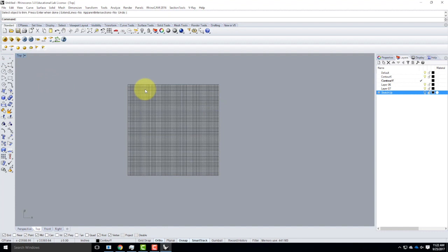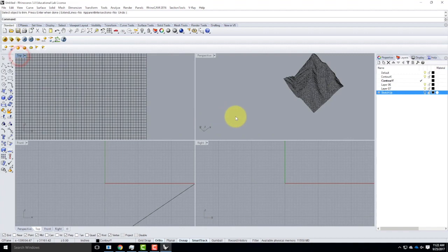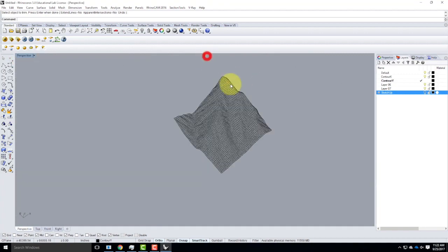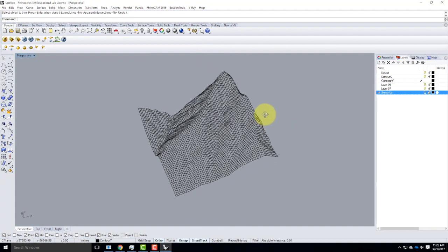If I had trouble doing the network surface, chances are the trim didn't complete correctly, or one of my contours wasn't perfectly aligned. It was off on an angle, in which case if I looked down at this, it wouldn't look like a perfect grid, which obviously it looks like a perfect grid, so everything turned out OK. So at this point, I have a nice contained set of curves here, and I can go ahead and do the network surface or the curved network to create the surface for this object.